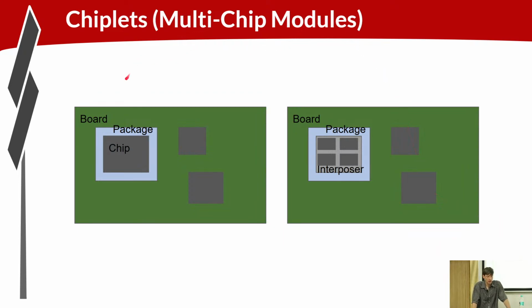One current trend that's going to be very important, right? So again, it's all about abstraction. How many layers of abstraction are in the process? As things scale and get larger and larger, eventually the existing stack of abstraction levels breaks and you need to introduce a new level of abstraction. That's what chiplets are all about. Where we used to have a single chip, we now might have a multi-chip package where we put multiple chips together. We slap an interposer on top, which is a chip that has all the routing to connect up the chiplets.